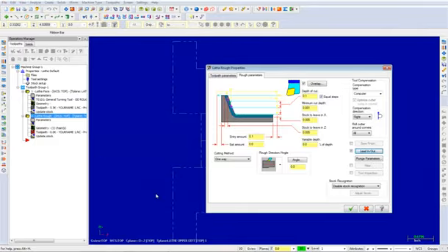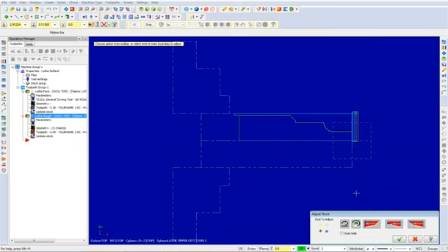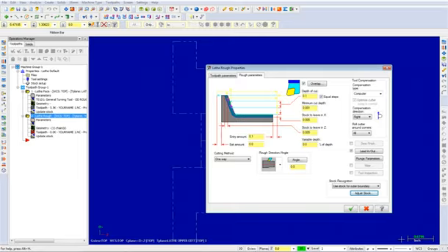In the Rough Parameters tab, change the stock recognition to Use Stock for Outer Boundary. When you enable the Use Stock for Outer Boundary, you will have the option available to adjust stock. Select the Adjust Stock button. When you click on the button, these options will appear. Now select the OK button to exit the Adjust Stock dialog box. Again, select the OK button to exit the Roughing Toolpath parameters.